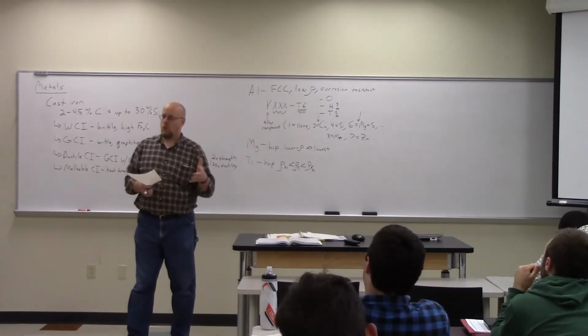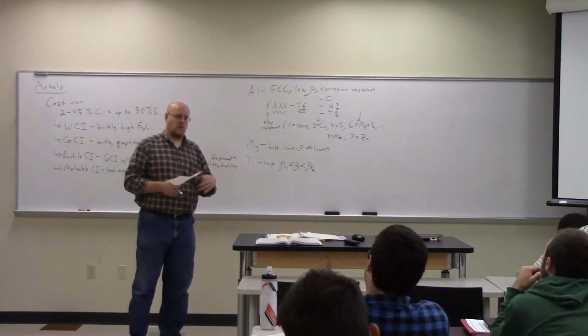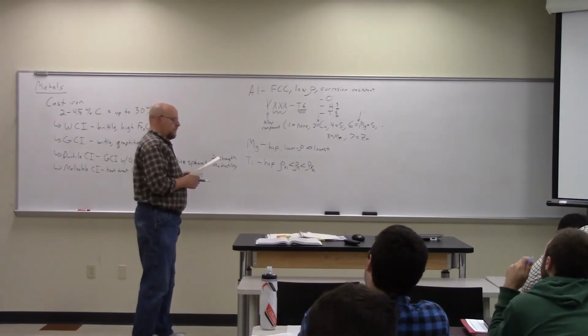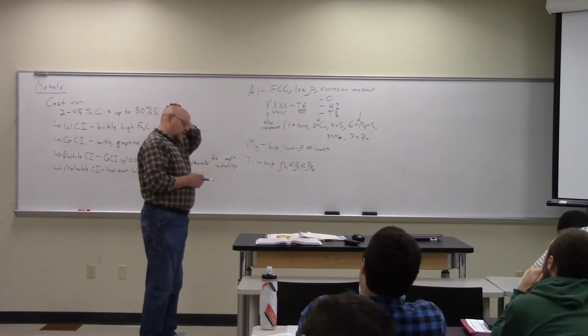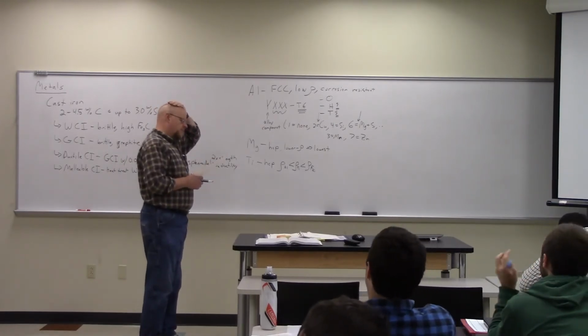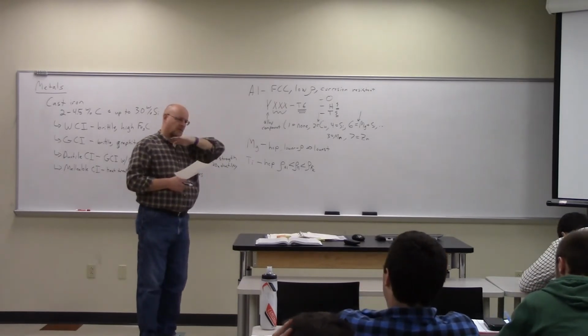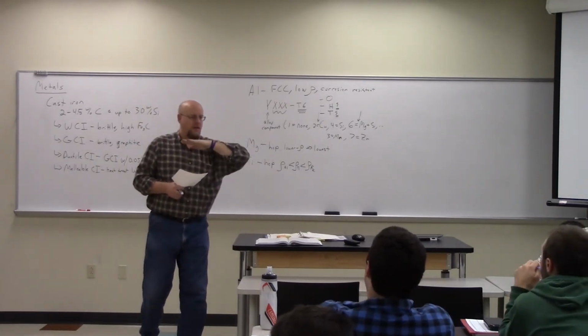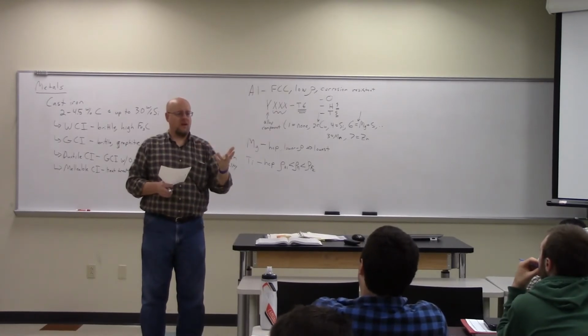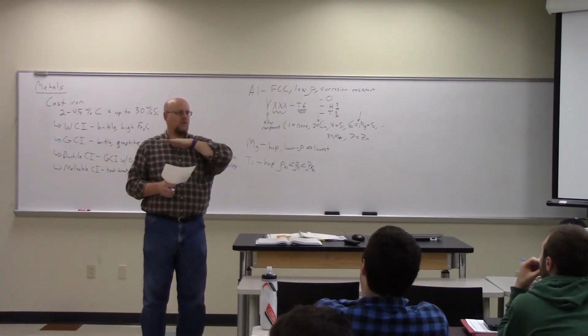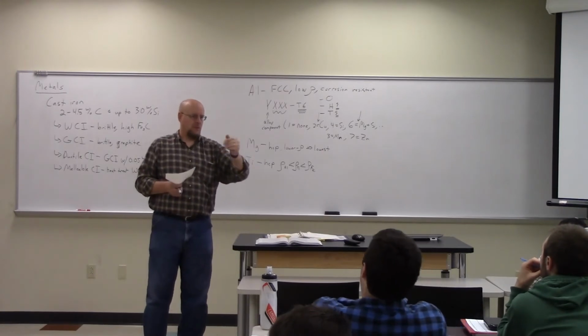Titanium doesn't corrode very well, certainly not nearly like steel does. What's passivity? The same thing I talked about with aluminum, that it forms an oxide layer that oxygen can't get through. So it's called passivating. It makes the corrosion process passive. Does that make sense?